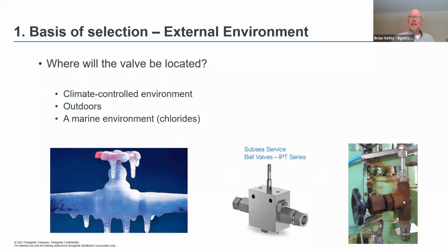And this is one that I included here. It was at one of my customers, where it was a temporary installation. Of course, there's nothing more permanent than something temporary. This valve was installed in a very corrosive environment. You can see it was a steel valve which corroded badly. It was only there as a temporary fix, and of course, it stayed there a little bit too long. It had a chance to corrode a little bit too far. We caught this one in time. There was no damage, nobody got injured, no environmental issues.